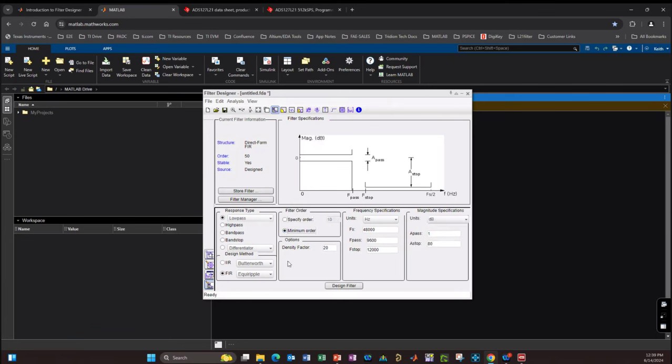And that's the example we'll use here. I had mentioned in the slide deck that we want a 256 kilosample rate. If you look in the L21 data sheet, you'll see that after this filter stage inside of the device, there is a decimation by 2. So the output data rate is 256. So this filter is actually running internal to the ADC at twice that rate because of the decimation of 2. So in order to design this for 256 output, we need to design the filter at actually 2 times that, or 512 kilosamples a second.